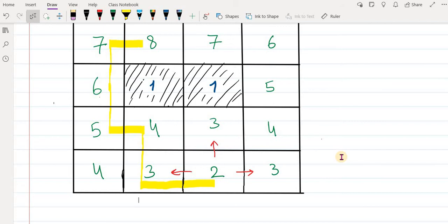So this is the best example. For example, imagine this is a 2D world, and here we have the robot arm located here, and actually no, it's not, it's a configuration space. So you cannot really tell the location of your robot using the configuration space, because this is most probably representing the position of your joint angles, θ1 on the horizontal axis and θ2 on the vertical axis.